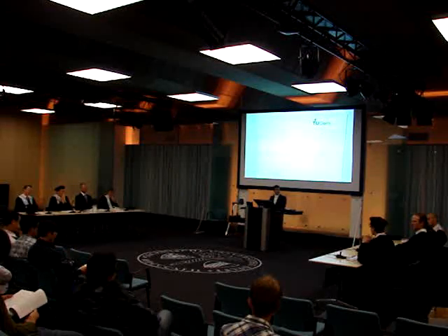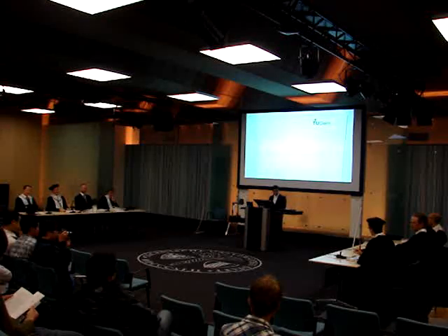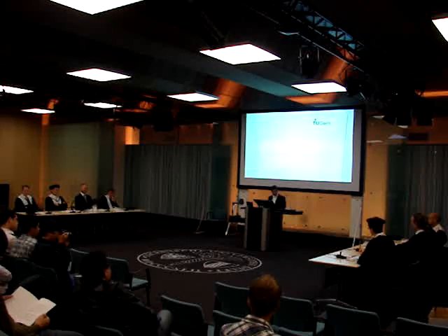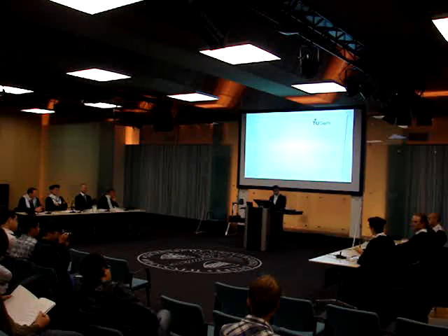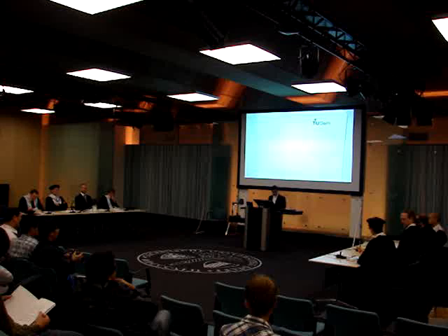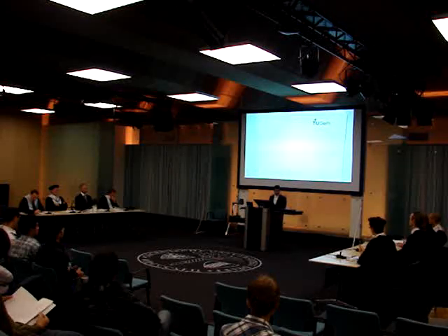Okay, I've got one final question, which is more technical. Basically, when you propagate the crack using XFEM, you have an old crack tip and a new crack tip, and you have now a new crack segment. Which means that you have new integration points which did not exist at the previous step. And you need to somehow initialize the internal variables at these integration points. Yeah, I made an assumption to avoid that difficulty.